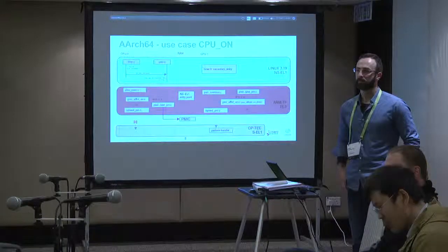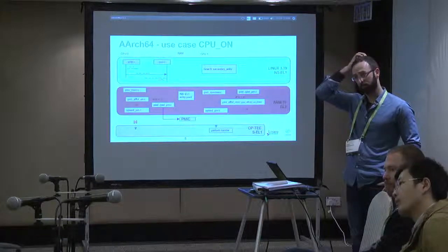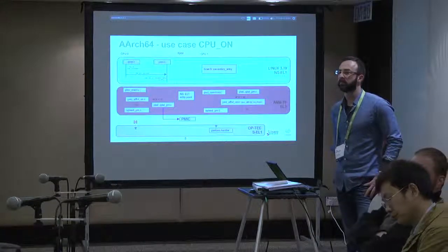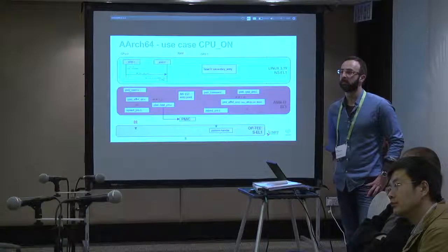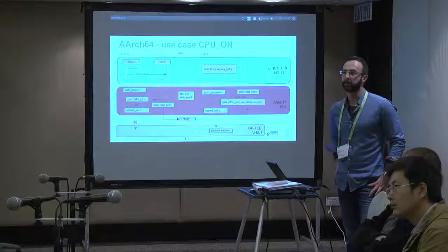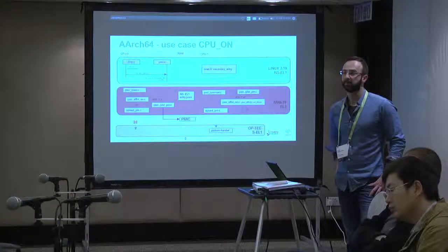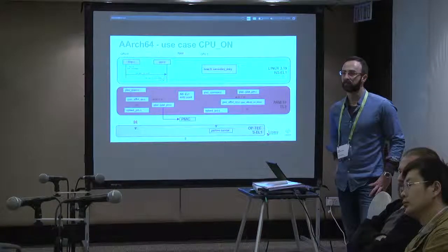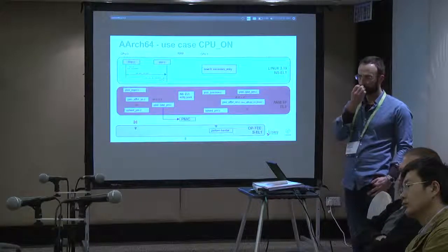Which is why you want to actually use the secure state and EL3 to carry out that stage of the processor exit from coherency. Not because you must do the actual power control invocation from EL3, but it's usually not possible to de-interleave that and do one thing first and then everything else afterwards. Hence the migration of the actual power control interaction to EL3, and trying to find a clean way of separating the two without having to do an undo operation one way or the other requires some careful thought, I think.